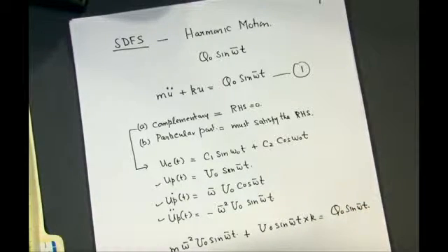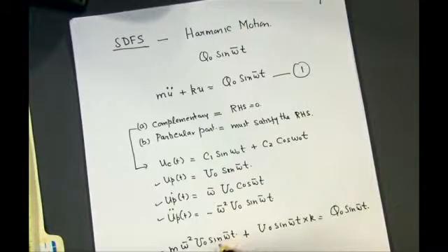Okay. Now in this equation you can see that sine omega bar t is common, and so we can write in simple form that our u0, which is the amplitude, is equal to q0 over k, okay, divided by 1 minus omega bar square over omega 0 square. Okay.